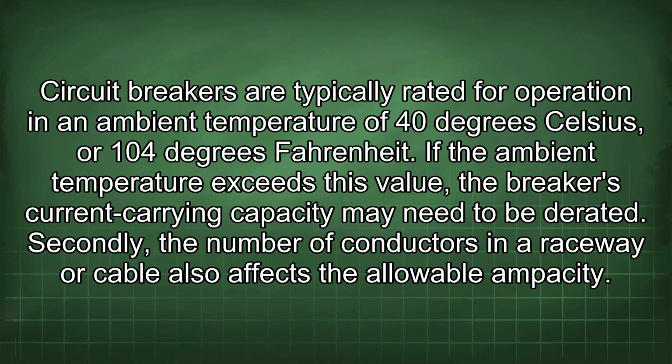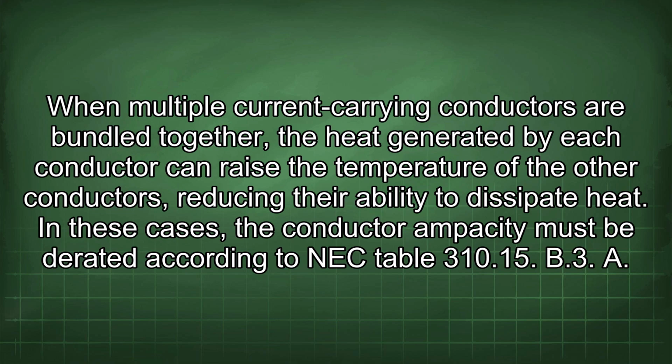Secondly, the number of conductors in a raceway or cable also affects the allowable ampacity. When multiple current-carrying conductors are bundled together, the heat generated by each conductor can raise the temperature of the other conductors, reducing their ability to dissipate heat. In these cases, the conductor ampacity must be derated according to NEC Table 310.15.